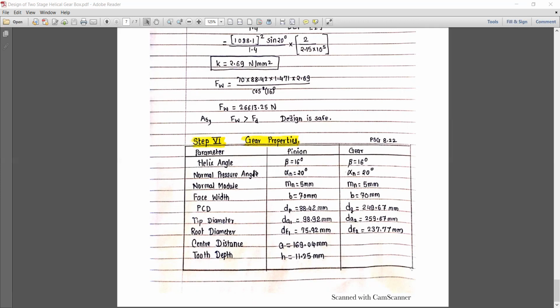Compare both stages, and design the stage where the speed is low. So what happens is that where the speed is low, definitely the torque is higher, and that stage only is going to face the huge torsional stresses. So if we design for the maximum stress once, it can be sustained for normal stresses also. So always find out which stage has more torque transmission.